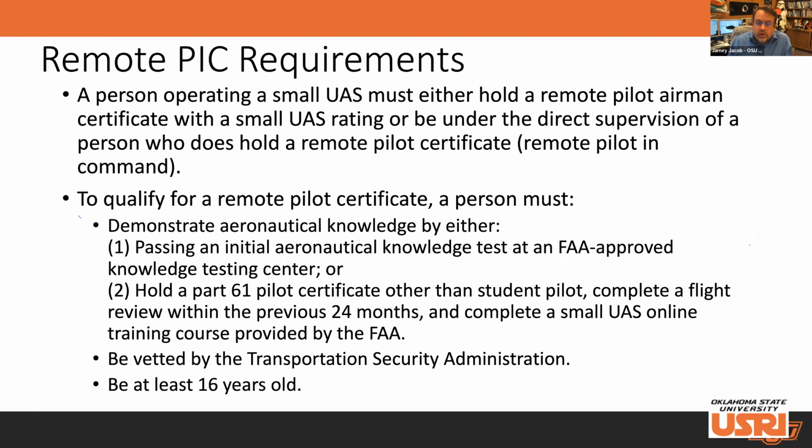Now, to be what's called a remote pilot in command, you must have what's called a remote pilot airman certificate. That means you take a test, you get your license, the FAA emails or mails that to you, and you have that card such that if you're ever flying, you can demonstrate to authorities that, yes, I am a licensed UAS pilot. Now, you don't necessarily have to be licensed if you're operating the aircraft if you have a PIC to serve as that direct supervisor.